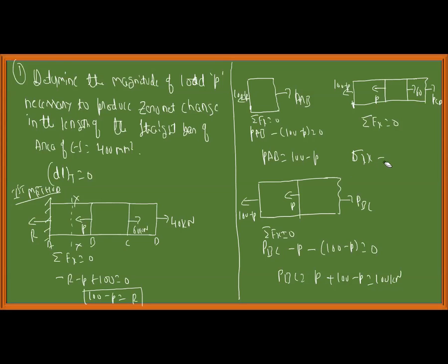If I take tau xy, it means the normal to the plane is x and the stress is acting in y direction. When we come to that, we'll discuss it. But you should know stress is a tensor, which also requires a plane on which the stress is acting.